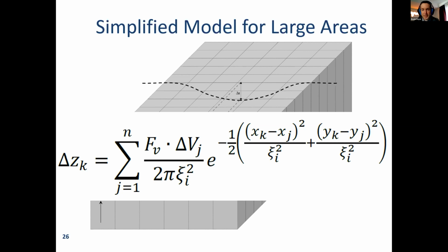Now, here's the key piece. Because we don't know where all the waste is buried, we don't know all of its properties in exact detail, we have to try out several different possible scenarios. This is where the stochastic modeling comes in. So we will, within a rule set that we generated, assign different changes in volume across the entire footprint, calculate the final surface shape, calculate how much ponding occurs, and then do that again and again for many different random configurations with the idea that we are trying to figure out what the extreme cases are that result in the most adverse drainage, but also what are some of the more typical cases that can result.